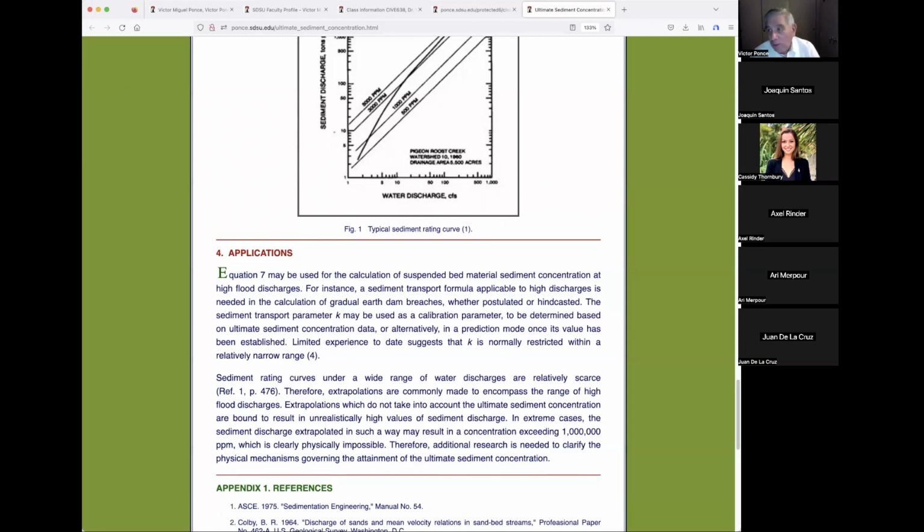Because all that water behind the dam is going to have to come out in, say, 30 minutes. Interestingly, though, for the dams that have been documented, and we actually have a paper on this, by the way, a documentation of time for the failure of dam breaches, we have proven through data, measurements and so forth, that it is usually a 2 to 3 hour breach, which is not good, but not bad either. It would be bad if it's only like 10 minutes, 15 minutes, because you can see the hydrograph would have to squeeze and concentrate and the peak flow goes up, and therefore you've got a major disaster. But nevertheless, we've got to figure it out.